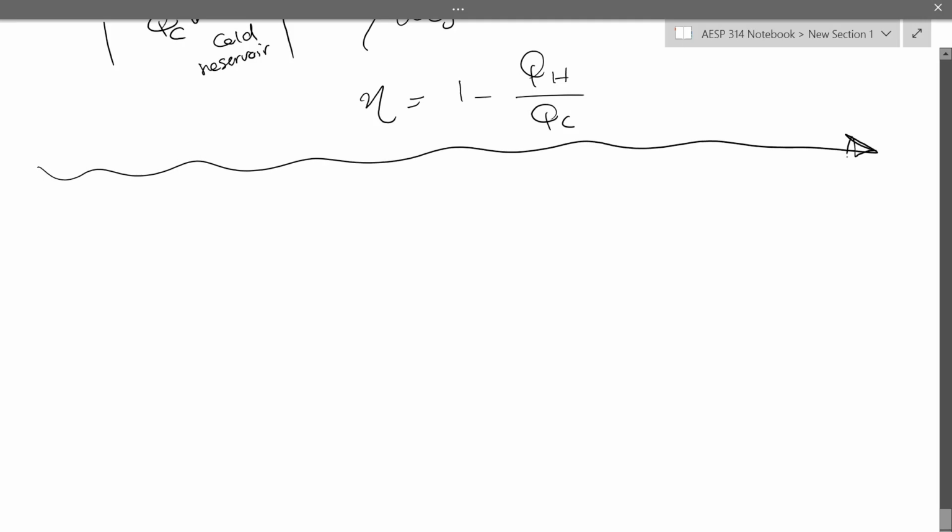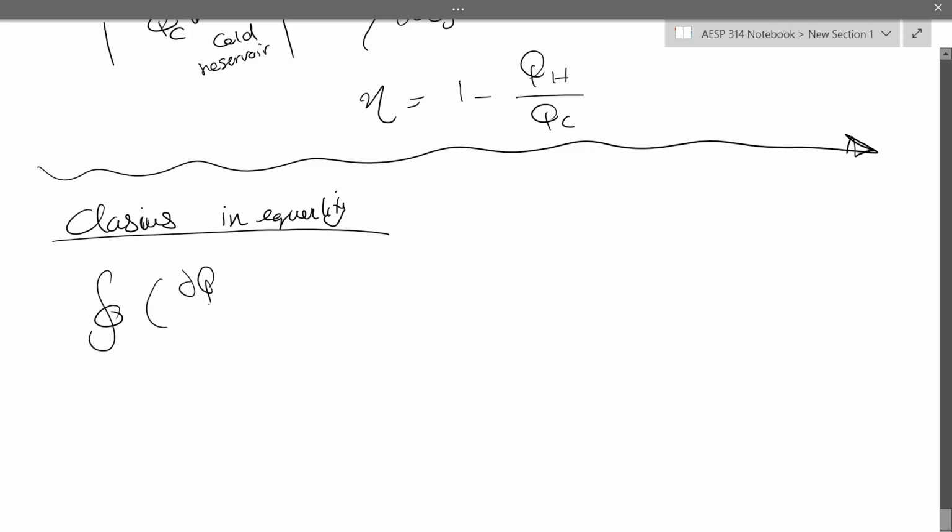Of course, as is true for any engineering course, we are really interested in formulating entropy. How can we calculate the entropy of a system, or how can we calculate the changes in entropy? We essentially define entropy using the Clausius inequality, that says the integral of δQ divided by T at a boundary of the system is always smaller than or equal to 0.